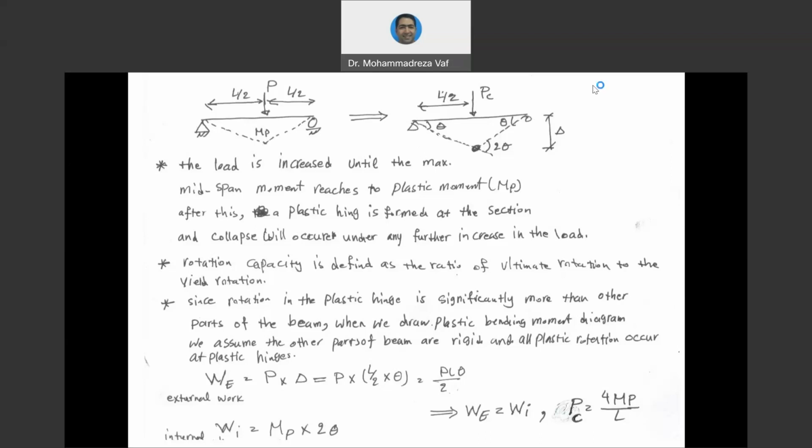However, let's say for the same beam, subjected to the same load, if the support condition was, instead of pin or roller, a fixed support. So you can see in the beginning of analysis, we don't have any hinge. In order to make this beam reach the collapse condition, we needed to have basically 3 plastic hinges. In that case, the beam could reach its collapse condition.